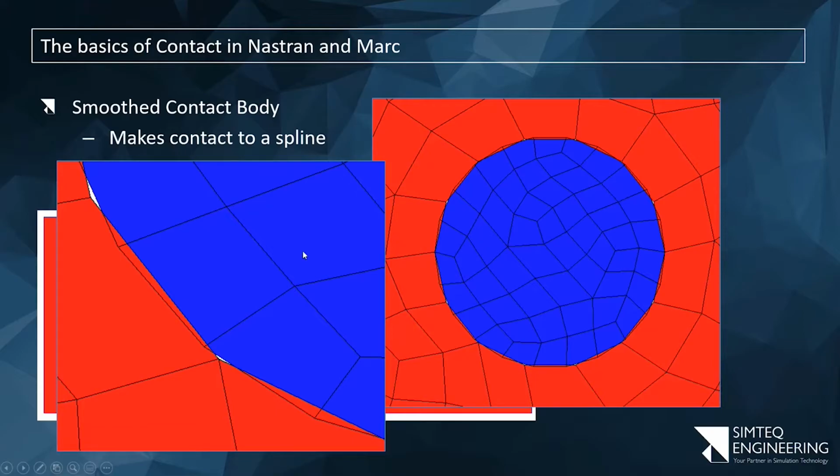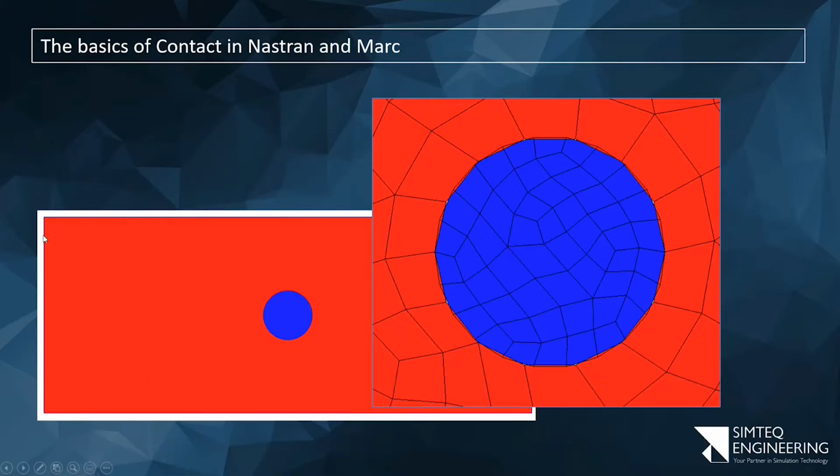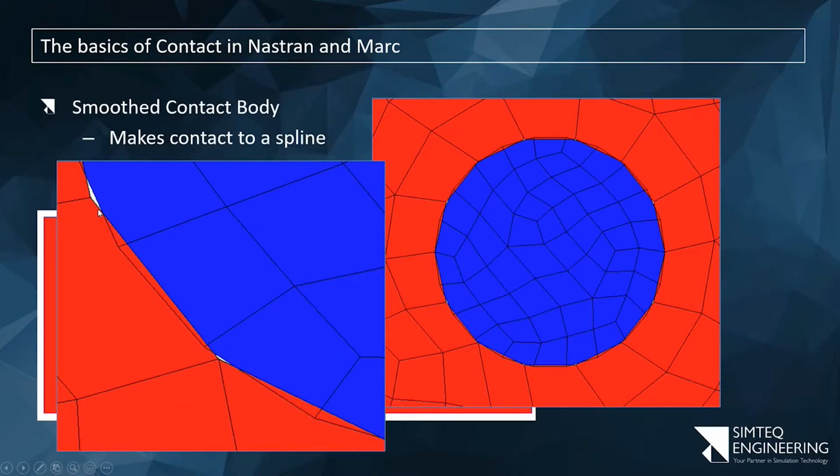It has to do with, if I just go back to this, what happens with the spline through a corner there. A spline says it has to be smooth. So what we'll see is a nice straight line there, and there at the end it does something funny and then it goes smooth again. To fix that, we simply need to specify this as a discontinuity, meaning it'll fit one spline through there and a separate one through there, and a separate one through that section. Okay, so this is a very convenient way to, even with a pretty coarse mesh, still get really good answers.